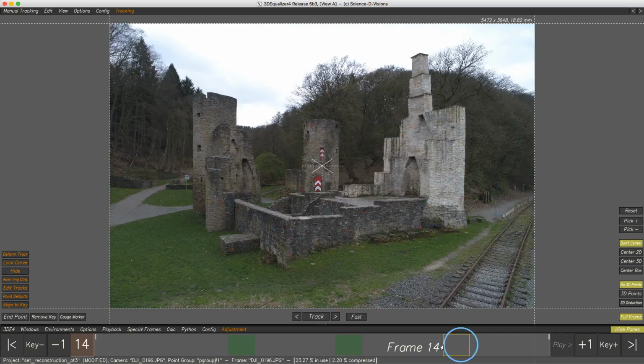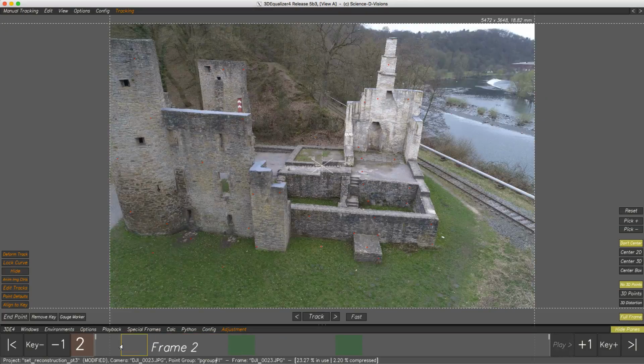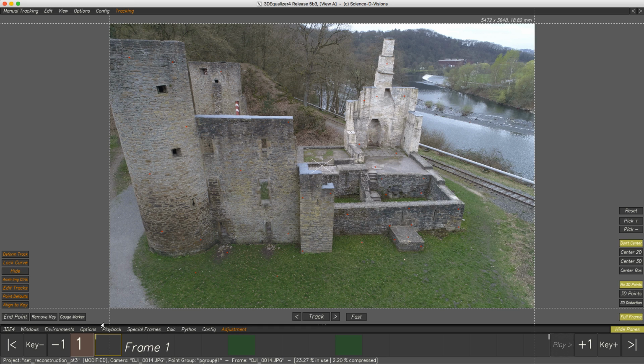Of course, there are plenty of frames that we can use, but for this demo, we'd like to go a bit extreme and use just the first 3 frames. Here, tower and ground can be seen very well, and we like to save some time, right? Using 3 instead of 17 images will improve performance drastically. But of course, this might influence the refinement quality. But that's why we modified sensitivity and quality.